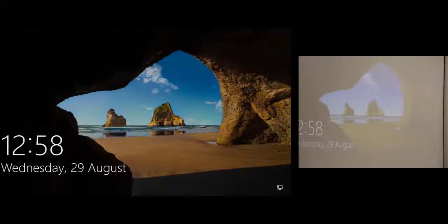What's the operation? The operation is basically, technically, looking at an odd number of ones in the input. If I have an odd number of ones in the input, I'll put 1. For a 2-input system, 1 is odd, correct? So that's why we say 0,1 or 1,0 is 1. This one is an even number, 0 or 2, so the output is 0. Oh, okay, so whenever it's 0 or 2 it will be 0, and when it's odd, it's 1. Odd number of ones.